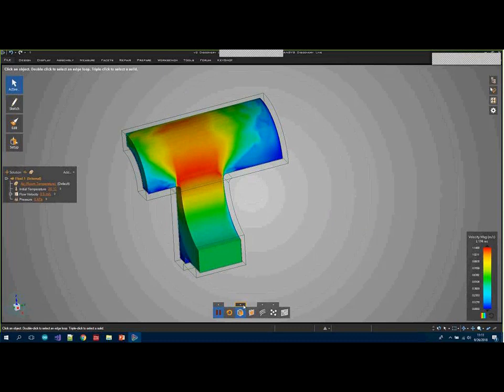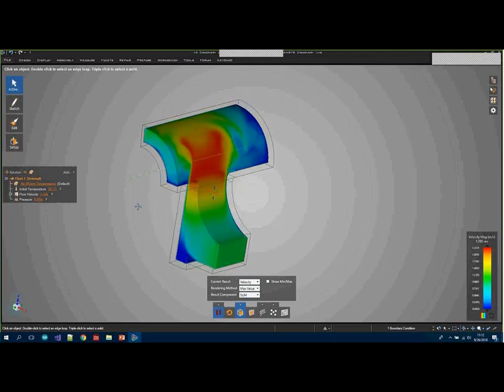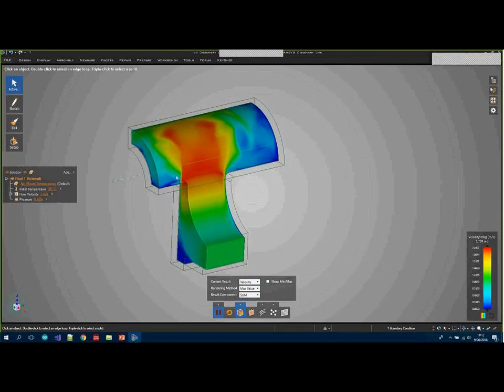And right now what we're looking at is the velocity, and we're looking at the maximum value. So currently in our solution, by default, we selected air at room temperature, which is 20 degrees Celsius. The flow velocity is here. It's currently set to 0.5 meters per second. We can increase that if we want to. Maybe I'll set it to 1 meter per second. And so you can see that it begins to update nearly instantly. So there you can see our maximum velocity highlighted in red.